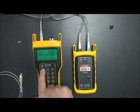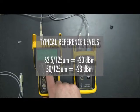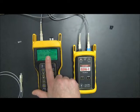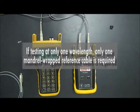And then just a review saying, are you sure you want to set the reference? And we do, so we'll press F1 to confirm. Save the reference, and now you can see that our reference level is minus 19.90 dBm. Okay, this is very good. Remember, we want to be roughly minus 20. This is very close. Now, since we're doing a 2 wavelength test, we've got to set the wavelength to 1300.